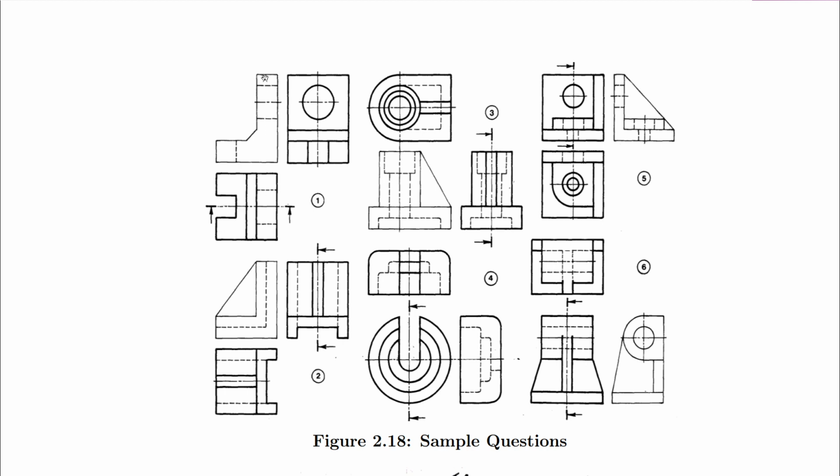There are some short dashes here with a center line. It tells us that there is a hole going through that section. We can also visualize that on the plan. On the plan, we also have some short dashes here, representing the same hole. On the front view, you can see this circle here, confirming that there is a hole in that section. It has center lines there. And the slot in front has been shown on the end view as this area here.